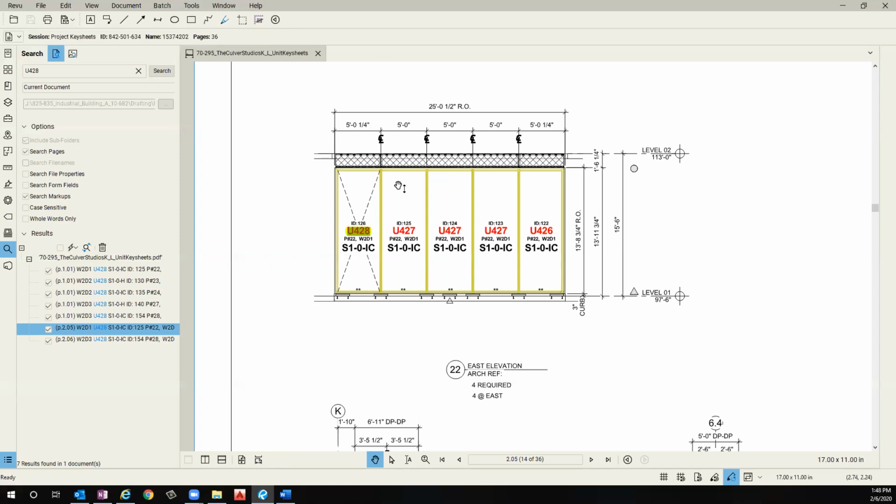So for example, we had a condition where we had a unit that was from a previous week, but on the current week that we were checking the duplicate unit, this bay had changed from 5'0" to 5'0" 1/8. So we realistically had to rebuild that unit and make it 1/8 of an inch bigger. So when that was the case, by checking these in each instance, even though it's a duplicate unit, we're looking at where it actually belongs on the building specifically for that week. We're able to identify that that unit wasn't really a 427, even though it had previously been named a 427.